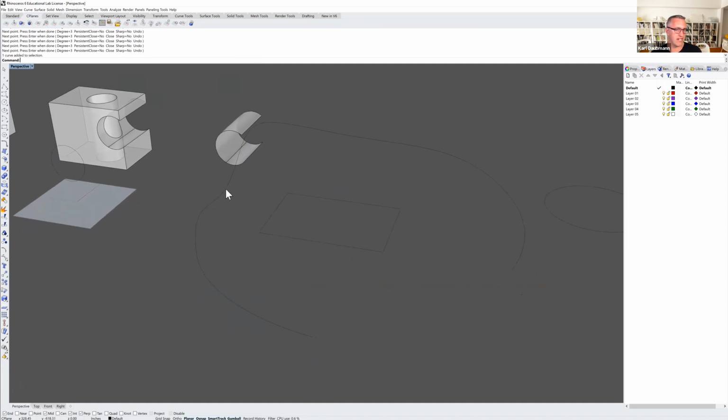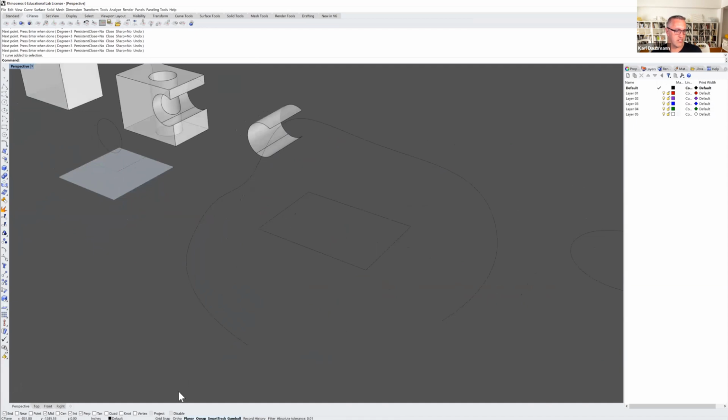One way to override that is projection. Down here at the bottom is a projection. It's down with the snaps, but if you have project clicked here, watch the difference. I'm drawing something, I'm not snapping to anything, but when I come over here, it is snapping to that corner point of that object, but then it's also projecting that point straight down to the construction plane. So project will override things that are in a different plane to force it back down to the plane.